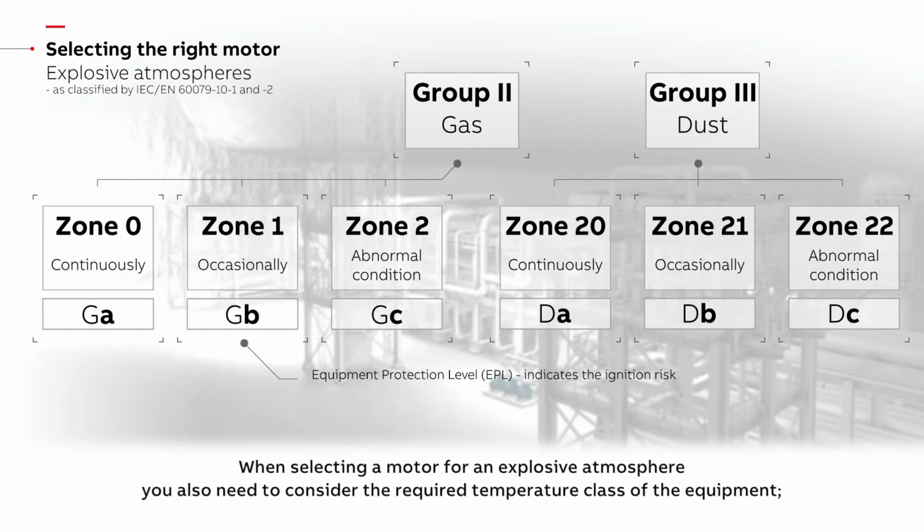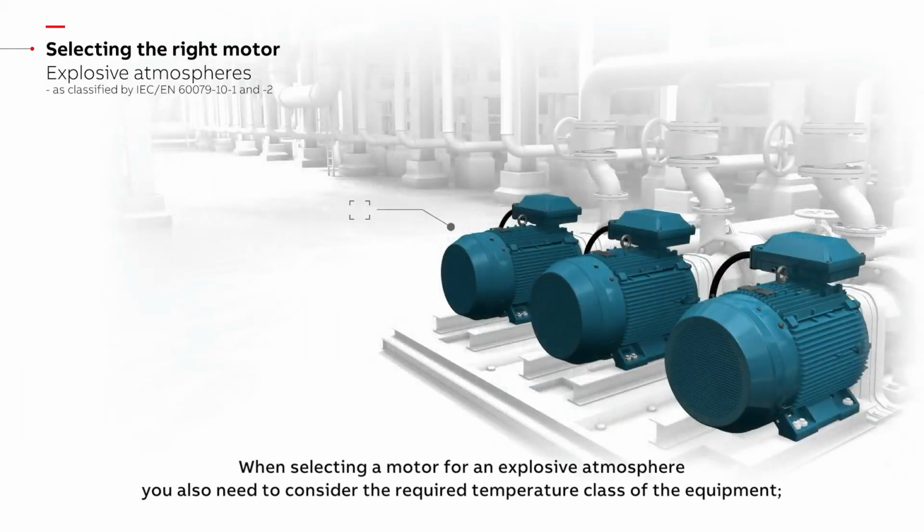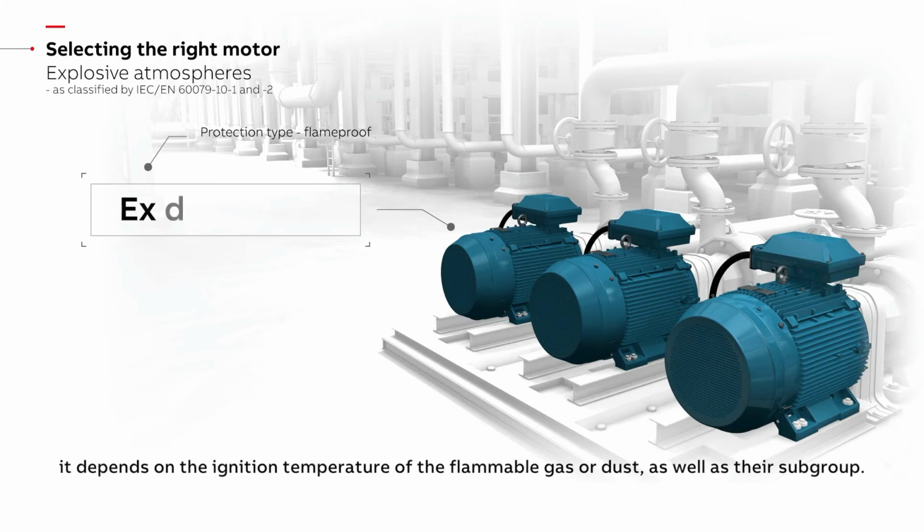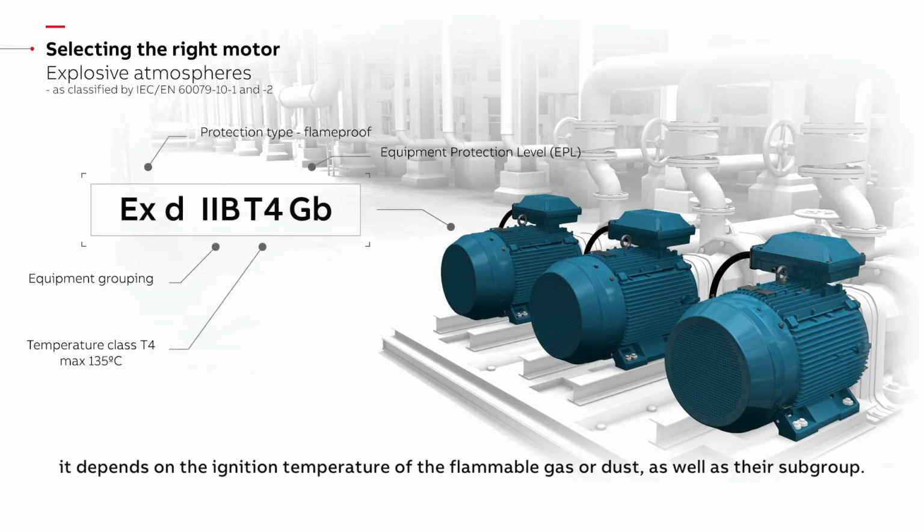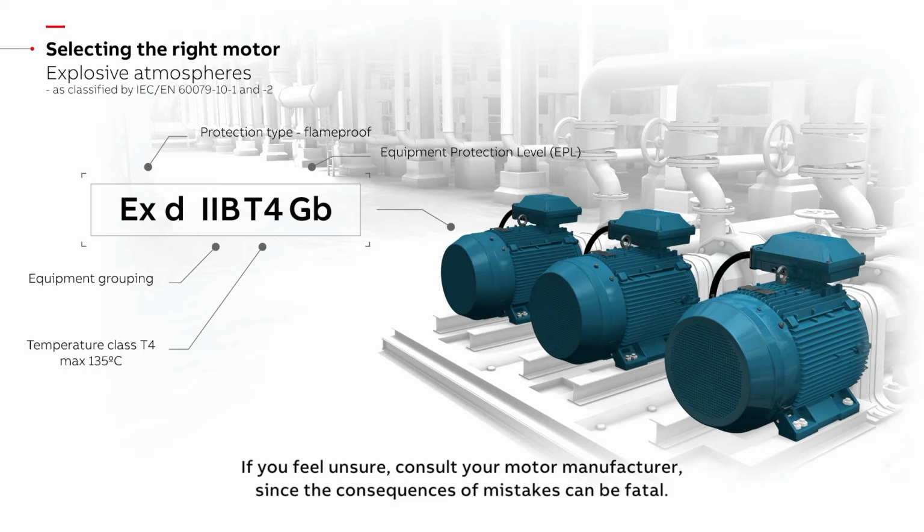When selecting a motor for an explosive atmosphere, you also need to consider the required temperature class of the equipment. It depends on the ignition temperature of the flammable gas or dust, as well as their subgroup. If you feel unsure, consult your motor manufacturer, since the consequences of mistakes can be fatal.